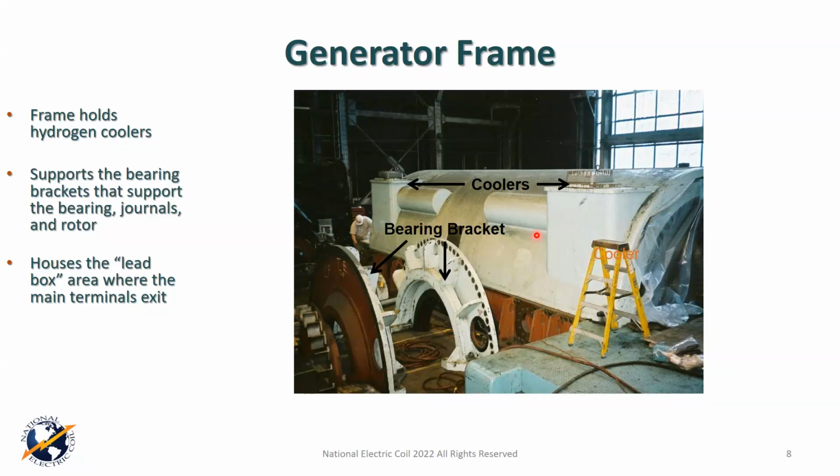And while we're talking about hydrogen, I want to put in a safety note. Probably won't get into it much today, but if your operation and your involvement in the operation doesn't include a good understanding of safely degassing your generator and policies on how you degas, who can degas, what your clearances are, and that kind of stuff, it's extremely, extremely important for your safety and the safety of everyone else involved to have a policy to deal with that.